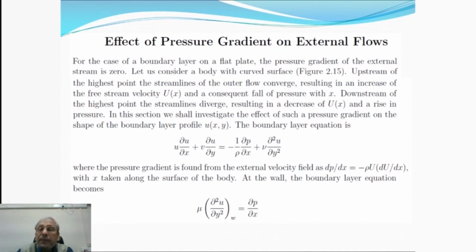Now, in the curved surface that we have already shown, upstream of the highest point, the streamlines of the outer flow converge, resulting in an increase of free stream velocity and a consequent fall of pressure with x.